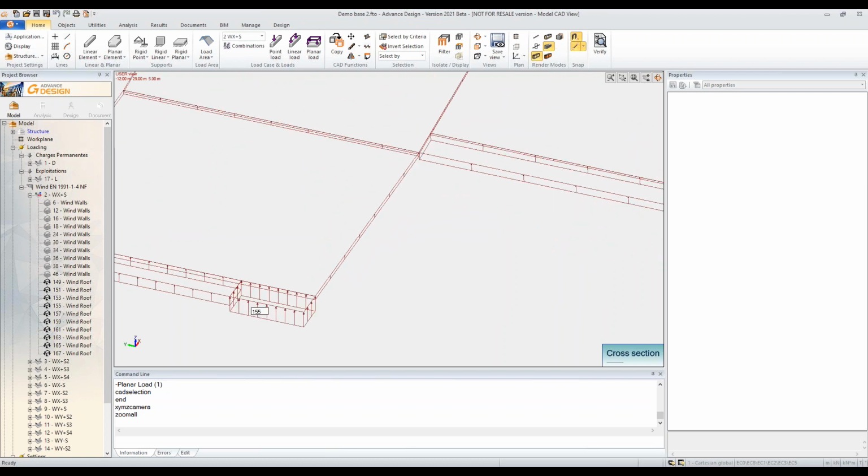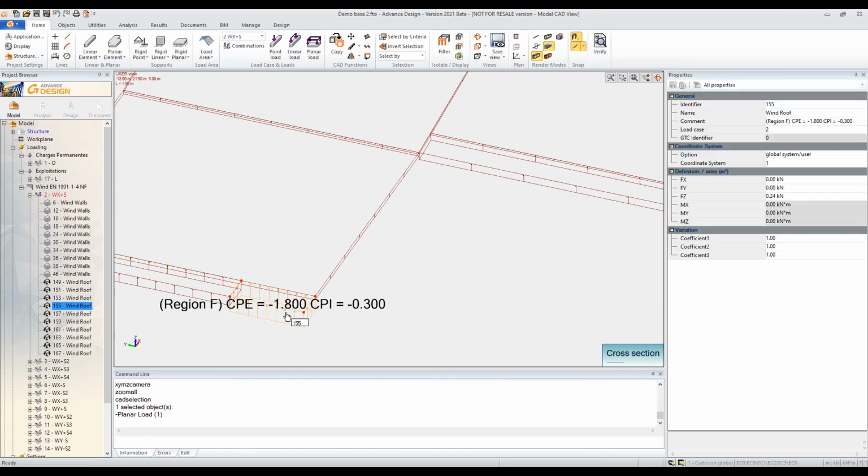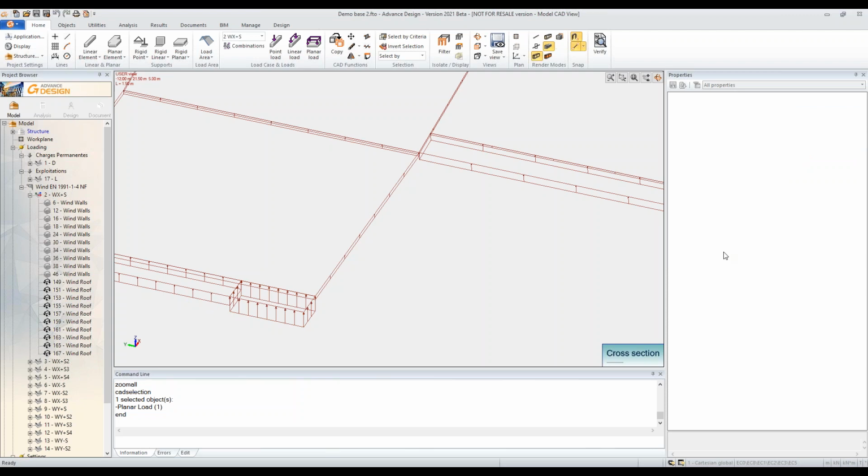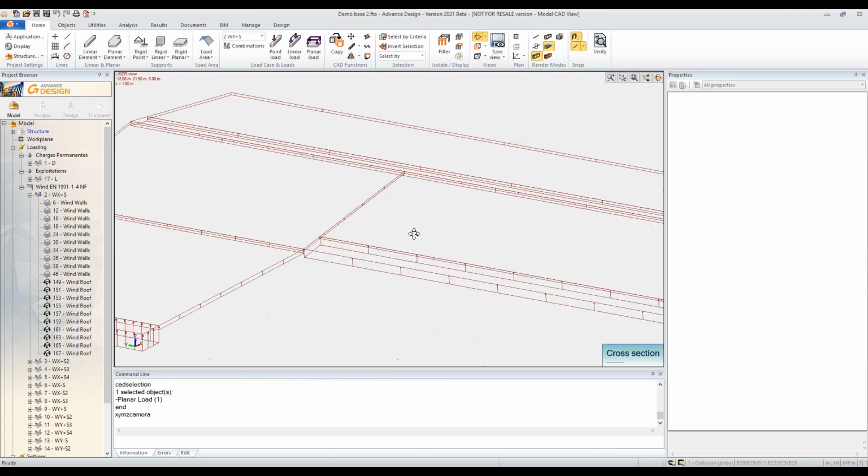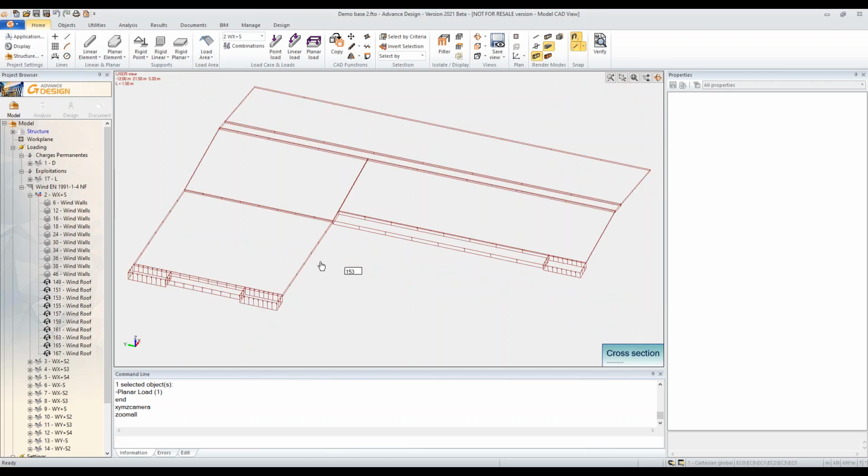First, you've got to find the zone dimensions. Like when you have a 3 meter by 120, you actually have to use a formula for each dimension. And then, once the zones are right, you have to find the right value for the pressure coefficient. This value you get after interpolating in tables. You have plenty of tables, so plenty of interpolations to make. So you have to do it for walls, roof, and for every single possible direction, and twice per direction. So yeah, manually it's a chore, and you will probably mess up in the process. So you need software to do that for you.